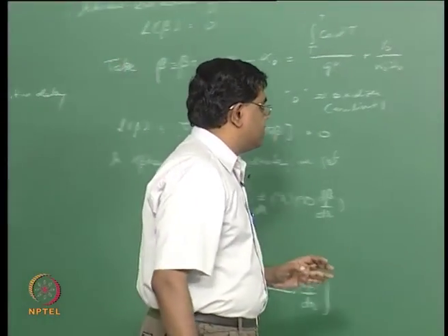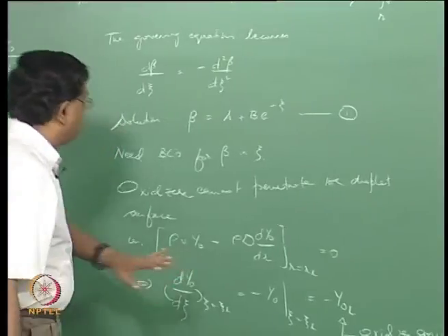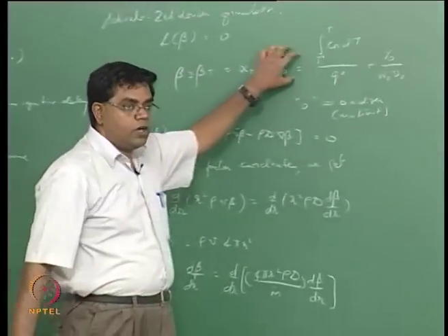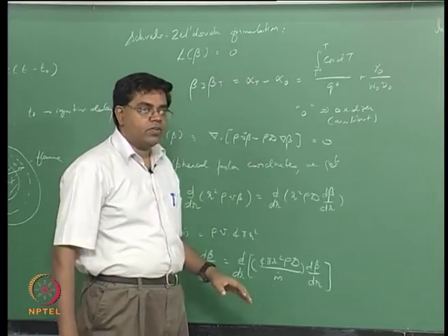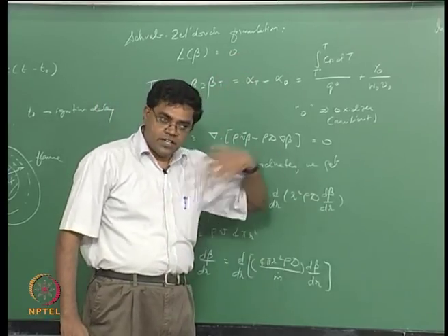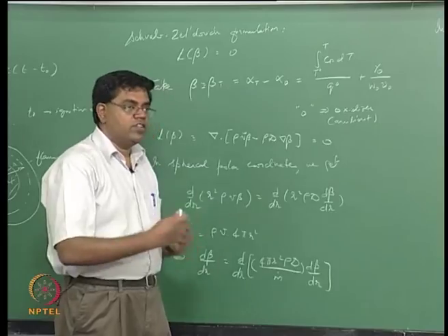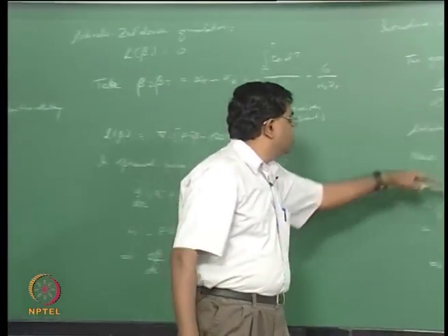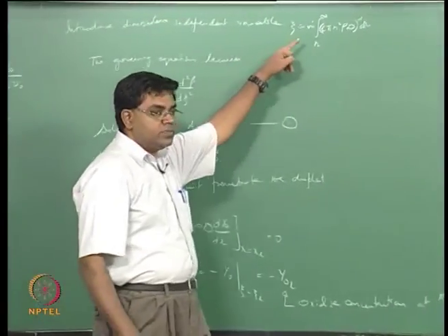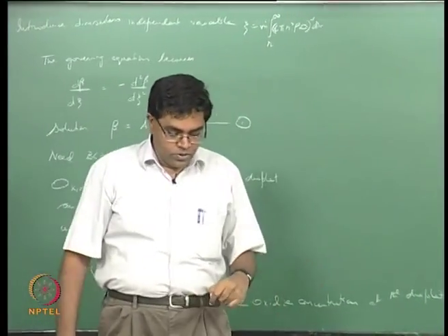So that's as far as one boundary condition for one component, alpha_O. Then we have to worry about what happens to alpha_T at r equals r_L, the corresponding ones at infinity, and so on. We construct these boundary conditions and the interface condition, and plug them into the solution in order to find m dot. That's essentially what we want to do. We'll do that tomorrow.